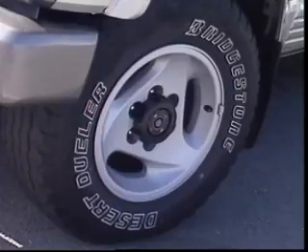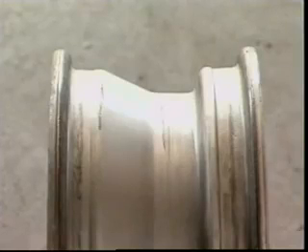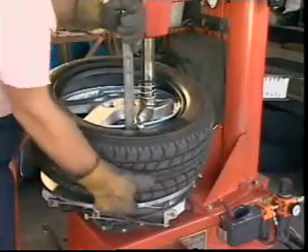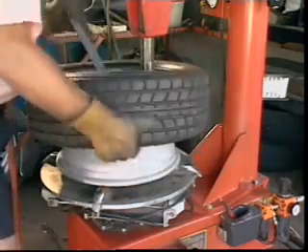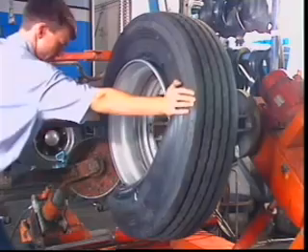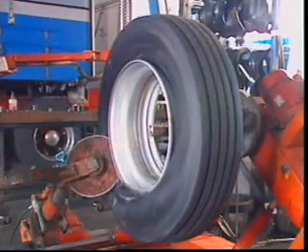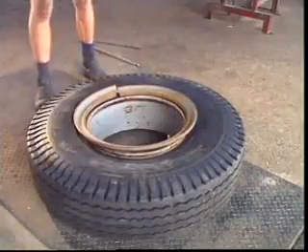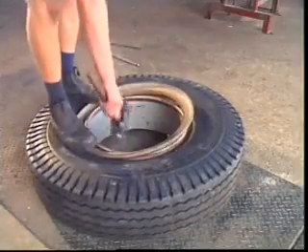Most wheels have ventilation holes in the flange, so air can circulate to the brakes. Most passenger car wheels are of well or drop center design. This design allows for tyre removal and fitting. Tyres for heavy goods vehicles are much stiffer, but they can also be fitted to a well-based rim or to a flat-based detachable flange rim, depending on construction.